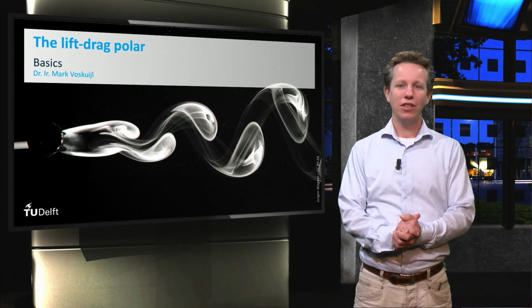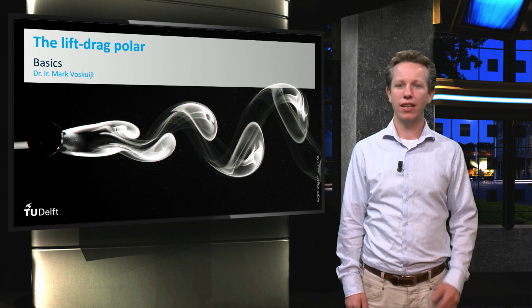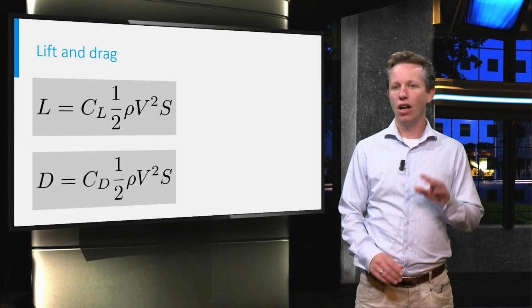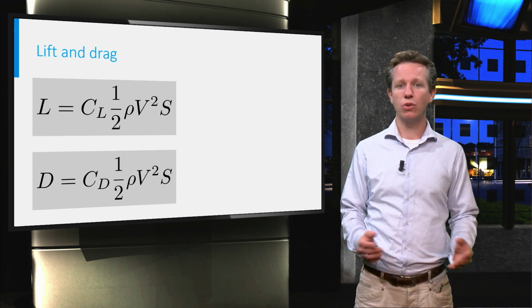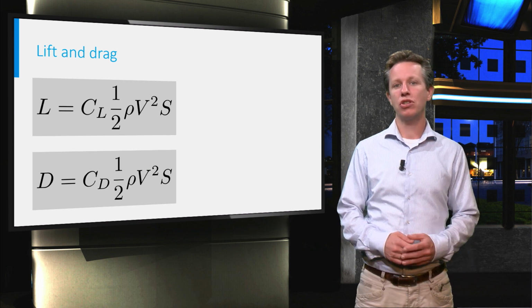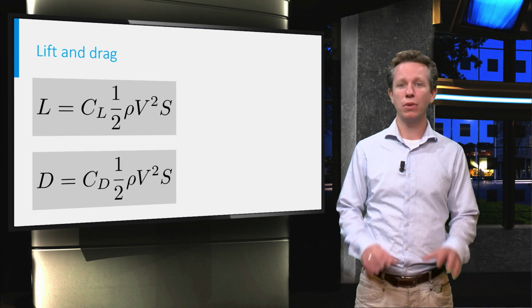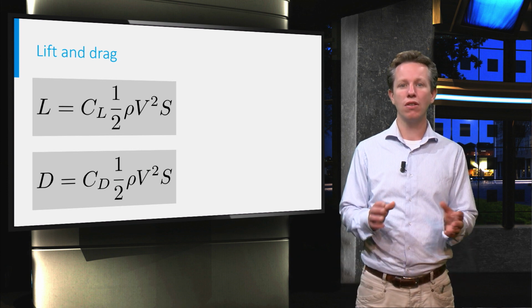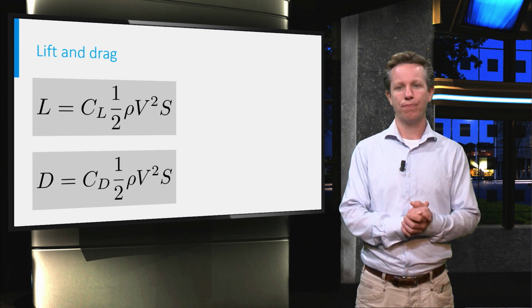Hello! Now that you have a basic understanding of the lift force, let's have a look at the aerodynamic drag. Along the same lines as the lift equation, it is possible to write down an equation for drag. It depends on a pressure, the dynamic pressure, multiplied with the surface area, and finally multiplied with a non-dimensional coefficient, which represents the geometry and the angle of attack.